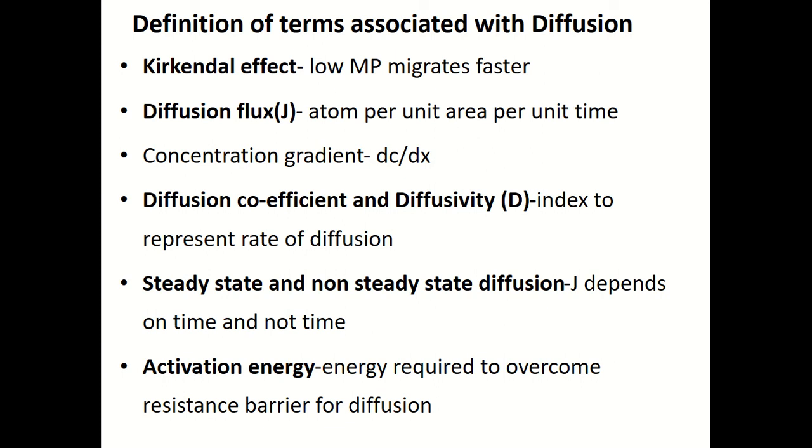So we already discussed the binary diffusion couple to demonstrate the phenomenon of diffusion. I hope you are remembering. So there, in a binary diffusion couple of metals A and B, the rate at which A and B diffuse into each other. We discussed the example of copper and nickel. I hope you remember the copper migrated to nickel, nickel migrated to copper. The rate at which A and B diffuse in each other are not equal.